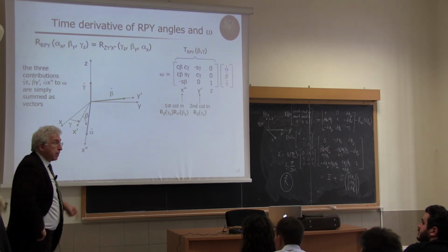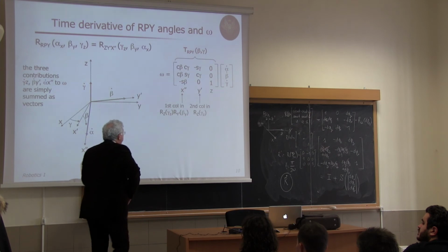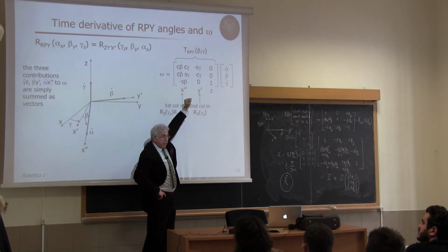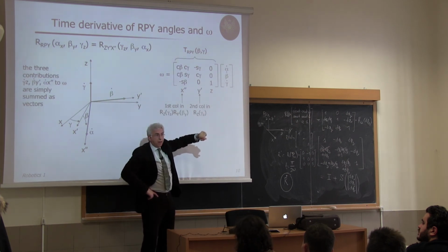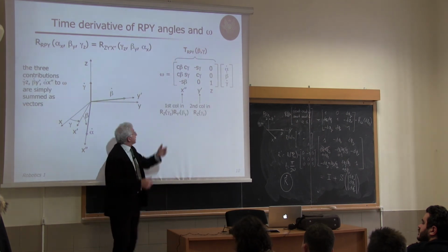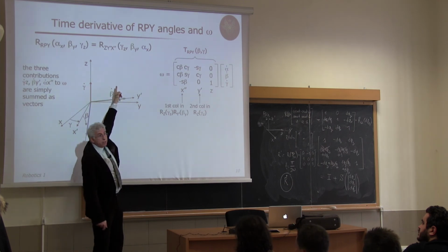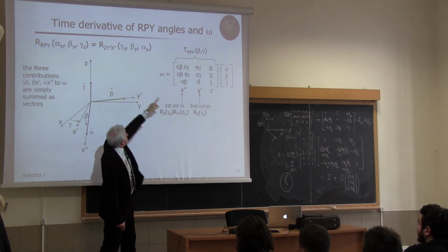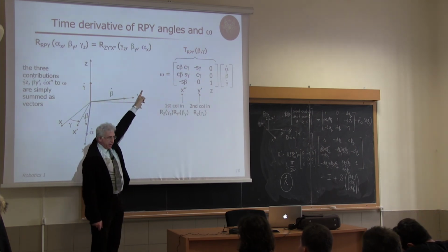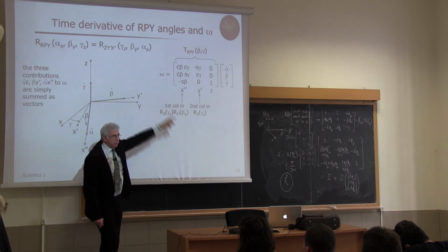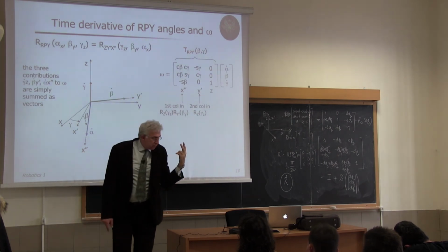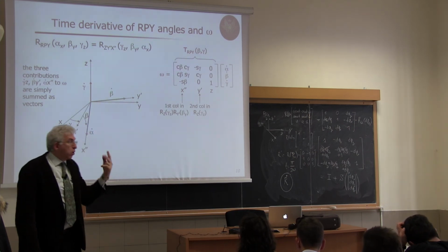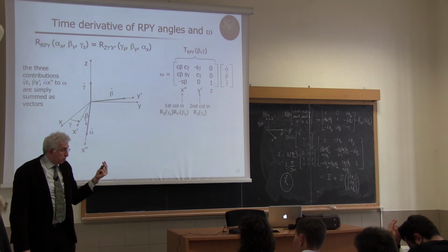And you see that if you're doing things around fixed axes, this matrix depends only on the second and third angle, and will never depend on alpha. Or if I'm doing this for that Euler sequence, z, y prime, x double prime, this matrix does not depend on the last angle, alpha. Okay? So it always depends on only two angles: the first two in a moving axis sequence, or the last two in a fixed axis sequence, just because of this equivalence.